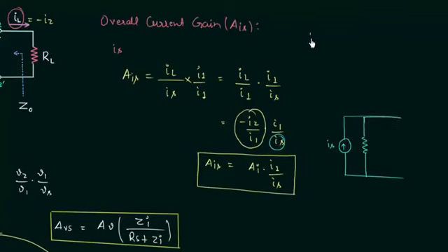The resistance RS is connected in series with the voltage source, and you want to convert it to the current source. Then you have the current source and the resistance. The resistance is now connected in parallel with the current source. This is basic thing to do. You can also convert the current source back to the voltage source.